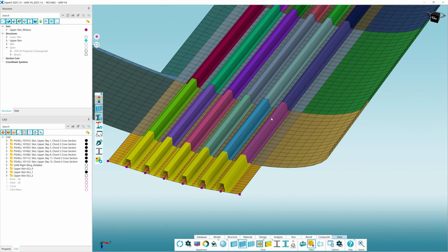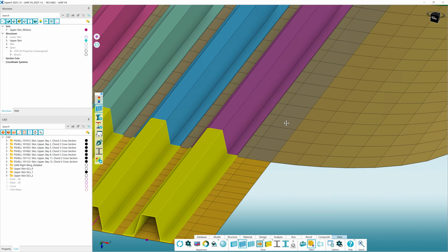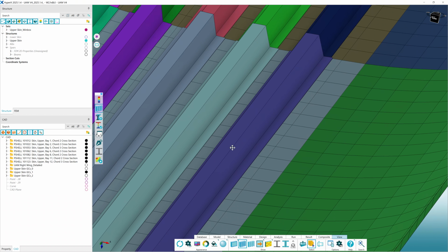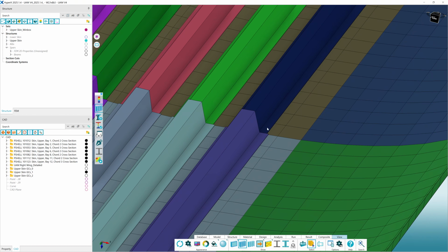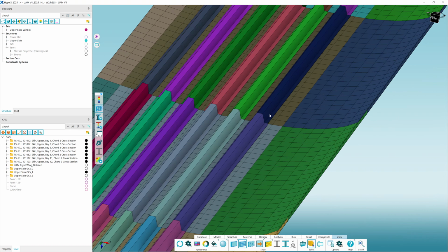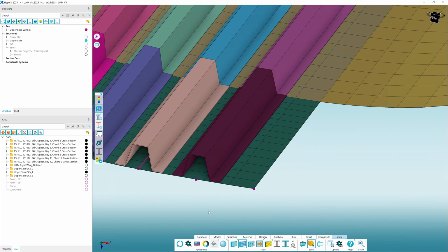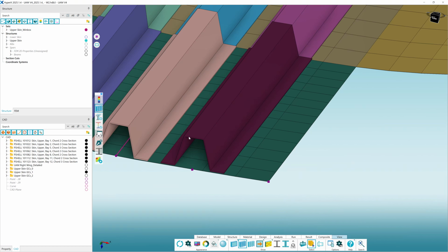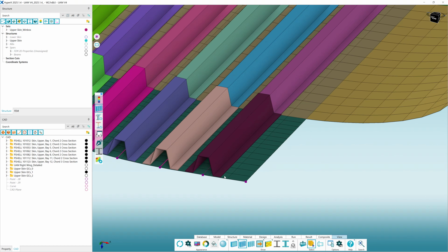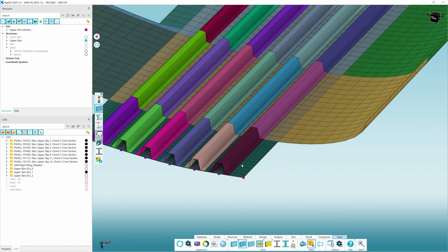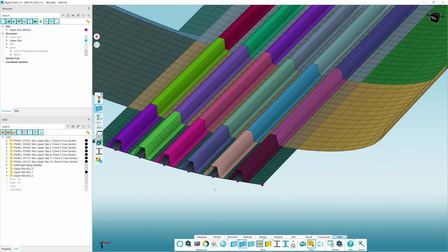And we can see that as we go down the wing, the stiffener height tapers, the spacing tapers, and the width of the stiffener also tapers according to our design property setup. And the thickness tapers as well, although it's a little harder to see since they're fairly thin. So yeah, we've now generated some stiffener geometry, and we're ready to maybe start iterating this with a CAD designer.